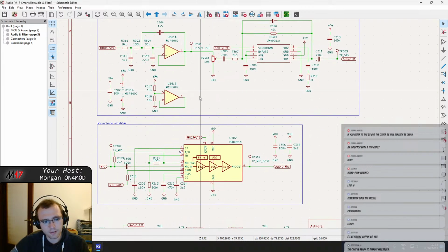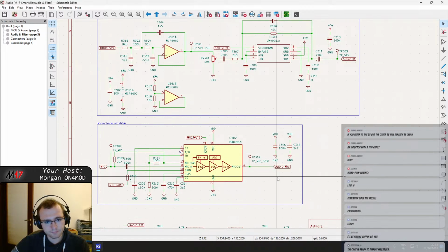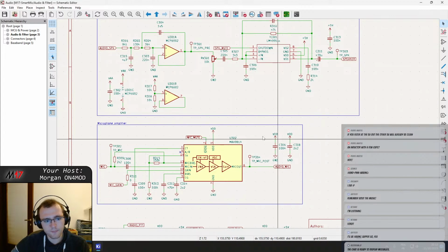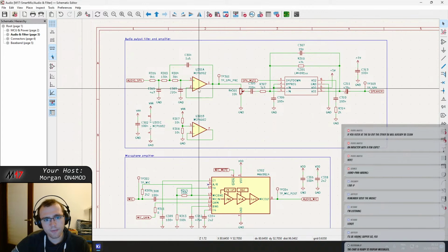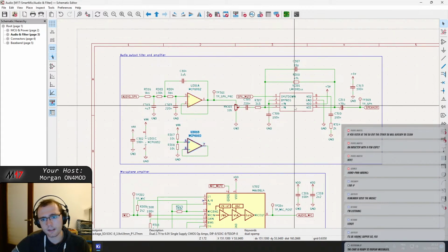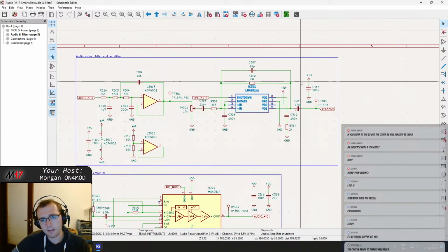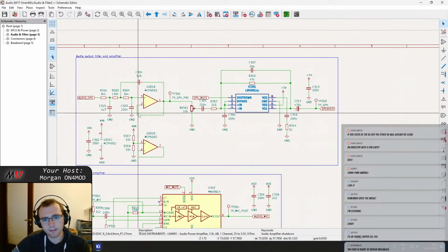Inputs, I don't think it can, because we don't have any 5V in the input path. In the output we have 5V on the filtering amplifier and the power amplifier, so ideally we would filter the 5V for all of this.